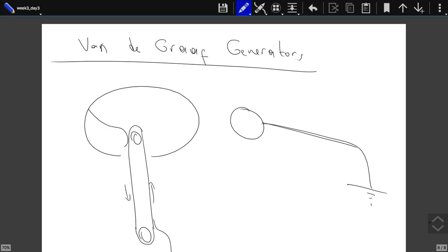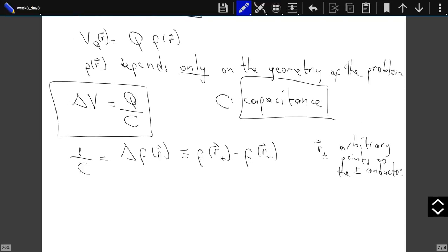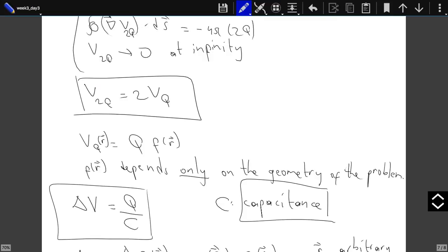Now the electrical breakdown is mainly determined by the electric field that you apply. So air can only support a finite amount of electric field before the breakdown. Let's see what the capacitance does. If you have a system that has a large capacitance, the potential difference in your system will be small, but the potential difference is proportionally related to the electric field. If the potential difference is small, that means the electric field is small. So there won't be an electrical breakdown.